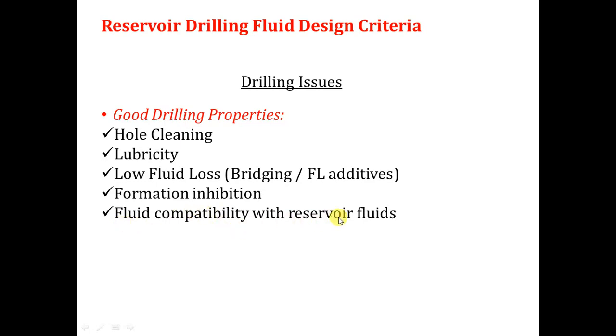The fluid compatibility with the reservoir fluids. The fluids that we are using, or the brine we are using, must be compatible with the reservoir in order not to make scales or cause damage to the reservoir and form skin, or make the skin factor very high, especially in the near wellbore zone.